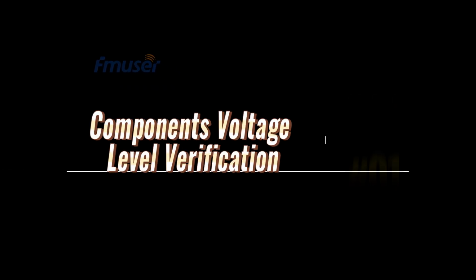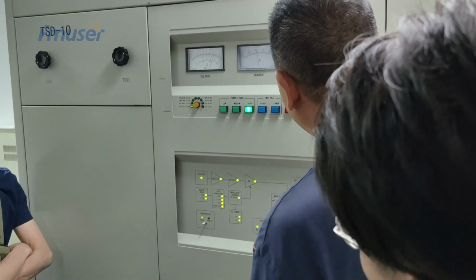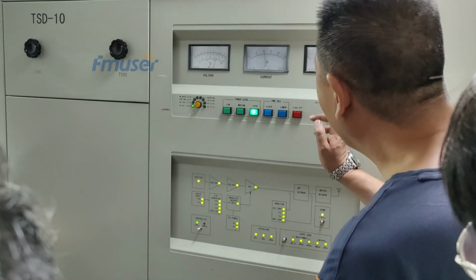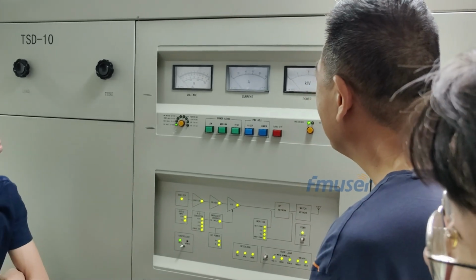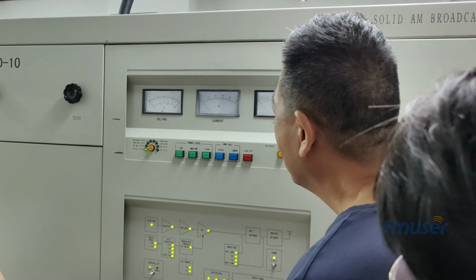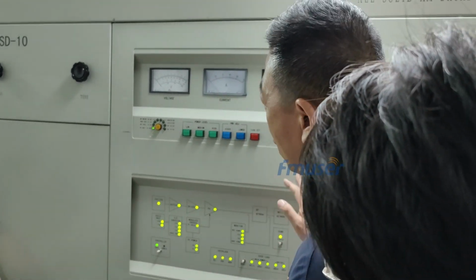Step number 1. Verification of voltage levels for key components. To ensure a safe startup process, begin by connecting the high voltage power supply to the transmitter, followed by the low voltage power supply. However, refrain from turning on the power amplifier at this stage. This step allows us to verify if the indicator lights on the control panel detect normal voltage readings for each module when the low voltage power is connected.